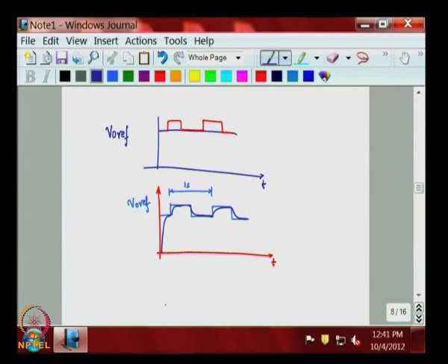And if you trigger the scope for this edge, then you will have a standstill waveform on the scope, and you could use the potentiometer to tune the Ki, Kp values to see the improvements in the transient response.